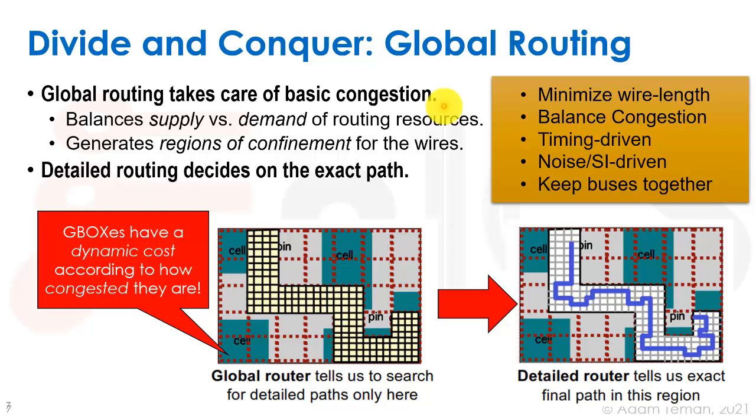So what we're really going to do is try to divide this into at least 2 stages, where the first stage, which would be global routing, is going to break our design into much more roughly detailed parts. We call them G boxes or global boxes, and you see that one of these boxes will have something like 10 tracks per layer on each side. That will be a G box. And then when we run our maze routing algorithm, we're not going to say that once we used a certain G box over here that it is blocked, but maybe that it has some sort of a larger number of options. So say we have 10 tracks going through this edge, if we use it once, we'll reduce that to 9 tracks. We used it again, we'll reduce it to 8 tracks, and so forth.